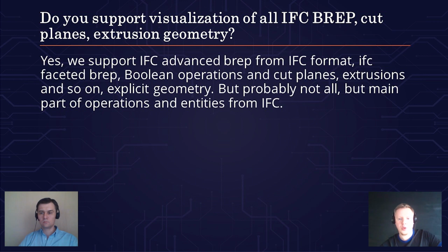Yes, we support IFC advanced BREP from IFC4, IFC faceted BREP, Boolean operations and cut planes, extrusions and so on, explicit geometry, but probably not all, but the main part of operations and entities from IFC.